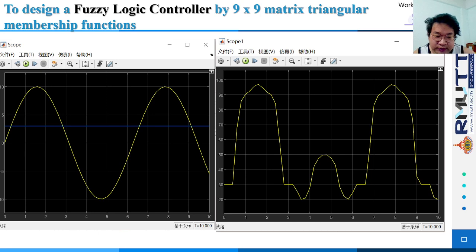It can be seen that without the fuzzy logic controller, the temperature fluctuation is larger because its control method is singular, and the energy consumption is also high, because regardless of the temperature difference, the cooling power operates in a fixed mode.